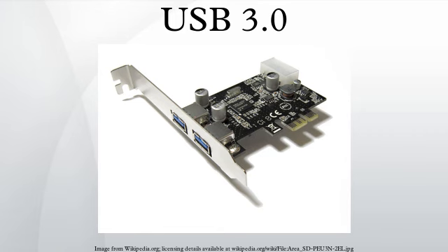Data transfer and synchronization. The SuperSpeed transaction is initiated by the host making a request, followed by a response from the device. The device either accepts the request or rejects it. If accepted, then the device sends data or accepts data from the host. If the endpoint is halted, the device shall respond with a stall handshake. If there is lack of buffer space or data, it responds with a not ready signal to tell the host that it is not able to process the request.